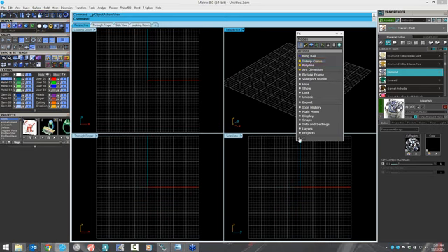You can populate the F6 command yourself. Okay, and you do that right down here with the gear. So click here to customize this menu. We have different categories. We have general mode, we have curve mode, gem mode, surface. We even have a user mode where you can just populate it with whatever you want. Maybe you want to do a smart target menu. You could do that in the user mode.